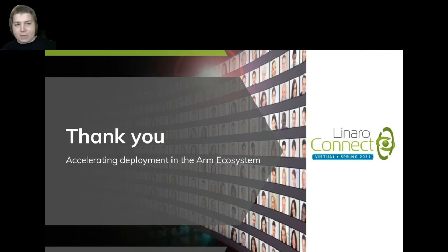Yeah, I can talk about something else personally. The Mezzanine specification talks about an EEPROM for automatic detection of boards, and then loading kernel modules and device tree. But that was never really implemented, unfortunately, which is really a bummer.